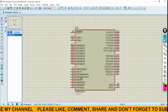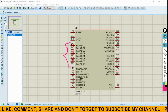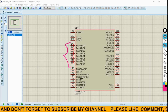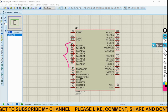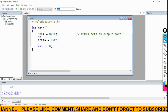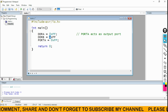You can see here port A is clearly reading, and the rest have no functions. We have not defined them at all. That's why they have the value unknown, not defined. We can see that we have programmed this particular port. So if we have to modify the code, we go into Programmer's Notepad and take another register, DDRB, suppose as 0xFF, keeping in mind 0.